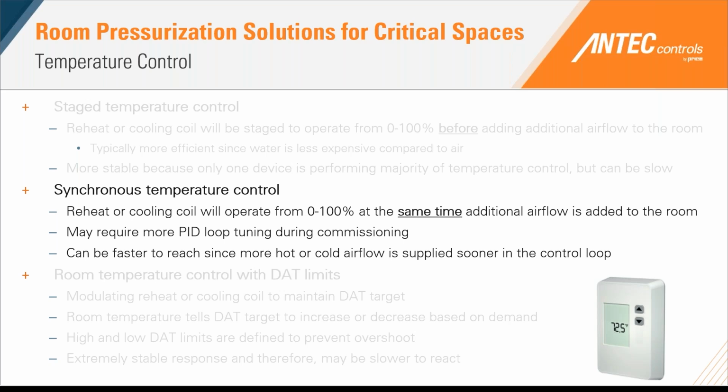So in this sense, we are now controlling our reheat coil between fully closed 0% to 100% fully open, while at the same time, we're adding additional airflow into the space. So because we're utilizing two devices, both the reheat and cooling coil and airflow at the same time to control for temperature, you can see very fast approaches to maintain set point.